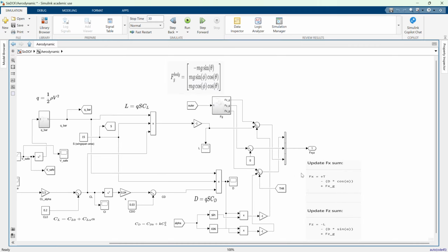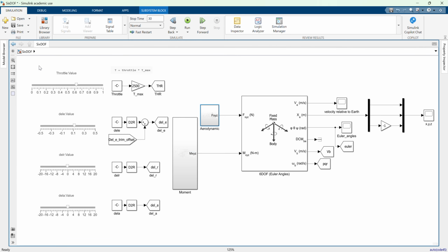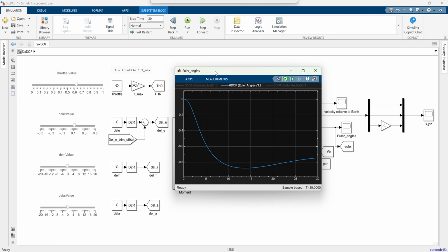And if you remember, we were fixing the sign convention with these negative signs. So that means let's make sense of all of this. If I give a positive elevator deflection, which means this airplane is pitching down, and I think for a normal airplane, if you are the pilot in the cockpit, that would make sense, right? If a positive elevator deflection, meaning you are pushing the stick away from you, which means the nose of the airplane is going down, hence your pitch angle is going down. I think that makes sense. With that being said, it's stabilizing but coming down, but then going back up again.